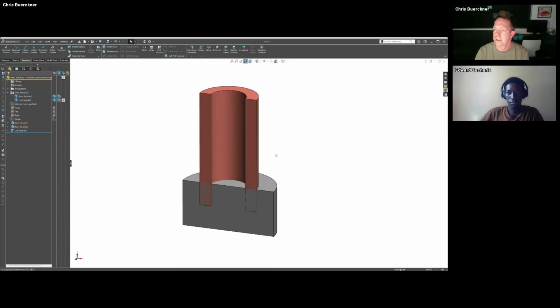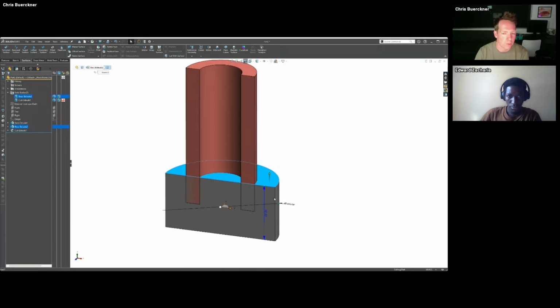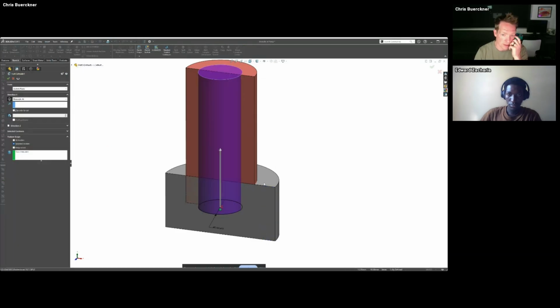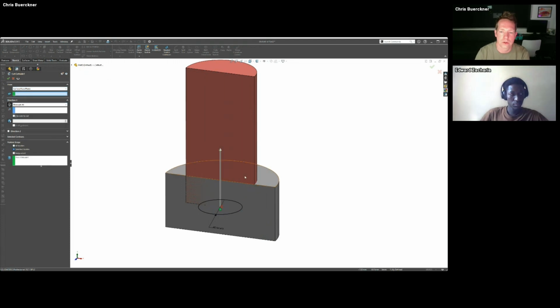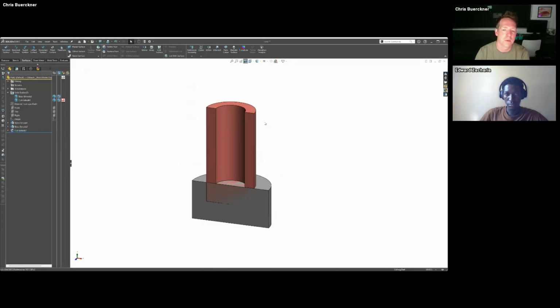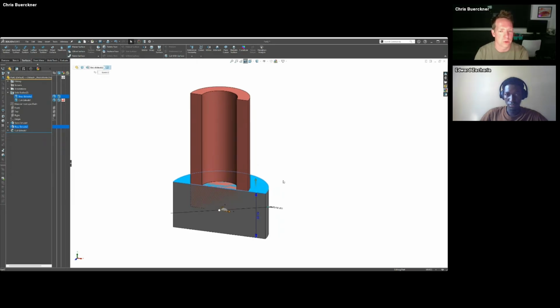All right. You can even change that again to, let's say, I want to reference this body. So I don't want the cut to start at the bottom. I actually want to use the face that I've created here and change my from, so the starting position of the cut, to this face. And so now my cut is using the reference of this second body we've created. It's not cutting through it at all, but it's cutting up through the red body.